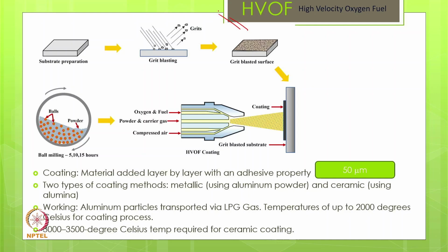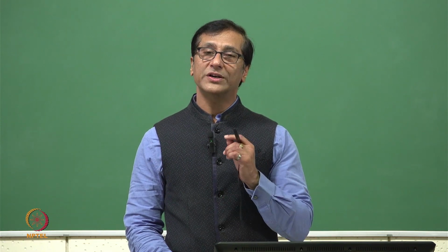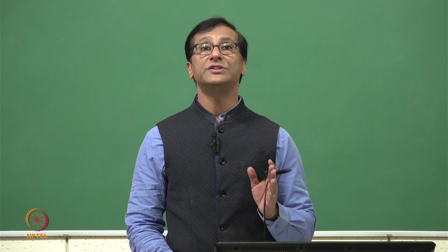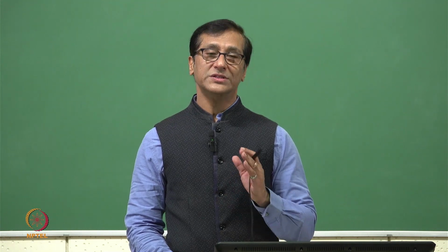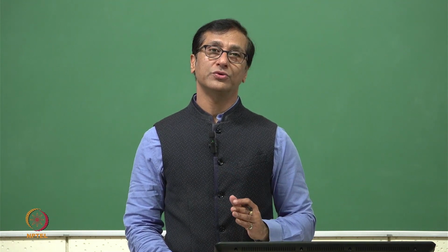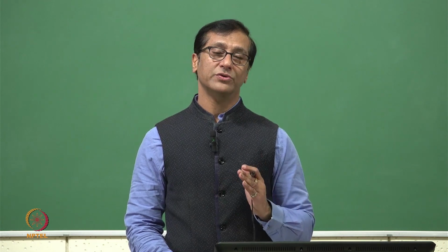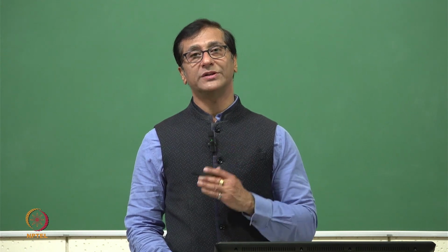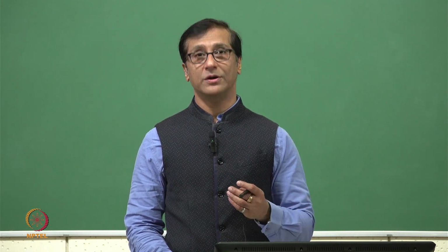Now we are continuing with the same. How do we prepare the surface? Basically we do grit blasting or something of the kind. You can see here it was a smooth surface, and it has been made a rough surface. So this is important. For tribological purposes, whatever manufactured surface we get, we generally do polishing. Now instead of that, if we directly come to the coating, a 1 micron, 2 micron, 5 micron coating, and that gives a good surface roughness, that will always be a better or more desirable option.